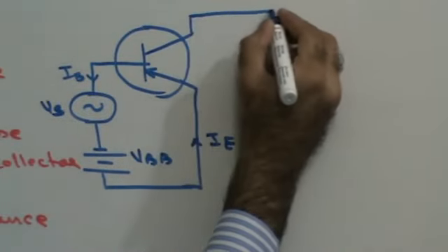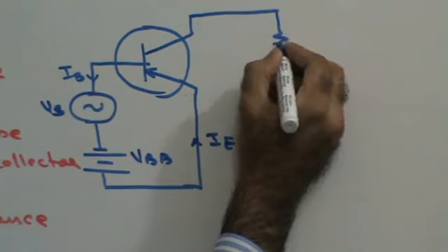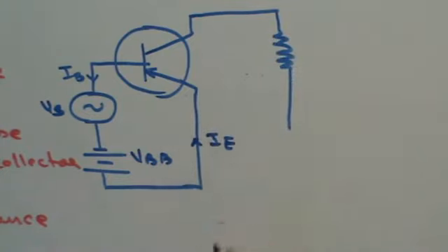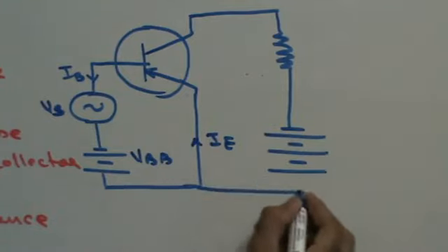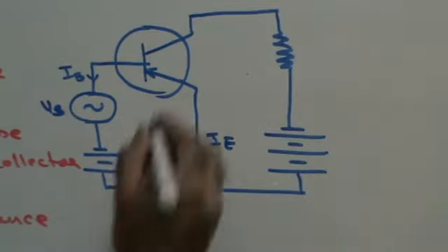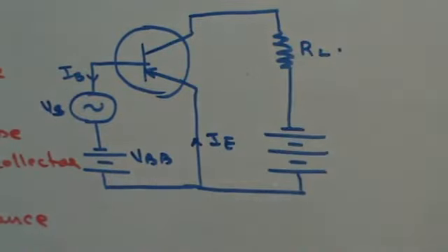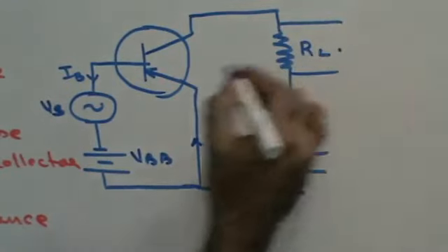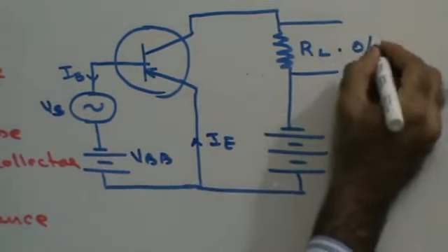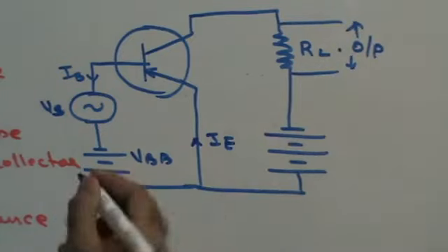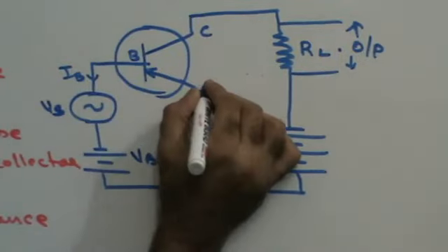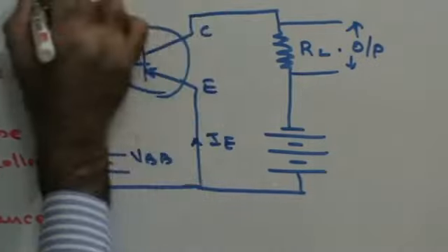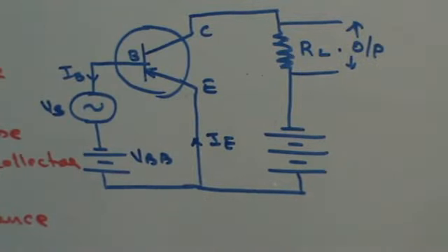You would measure the output across the load resistance. Now the output has to be reverse biased. So this is going to be my potential to reverse bias the output, right? This is my load resistance RL, across which the output is going to be measured. So the output is going to be measured across these 2 points. Fine. This is your collector, base, emitter. This is how you connect a transistor so that it can be used as an amplifier. Fine, do we get this thing here?